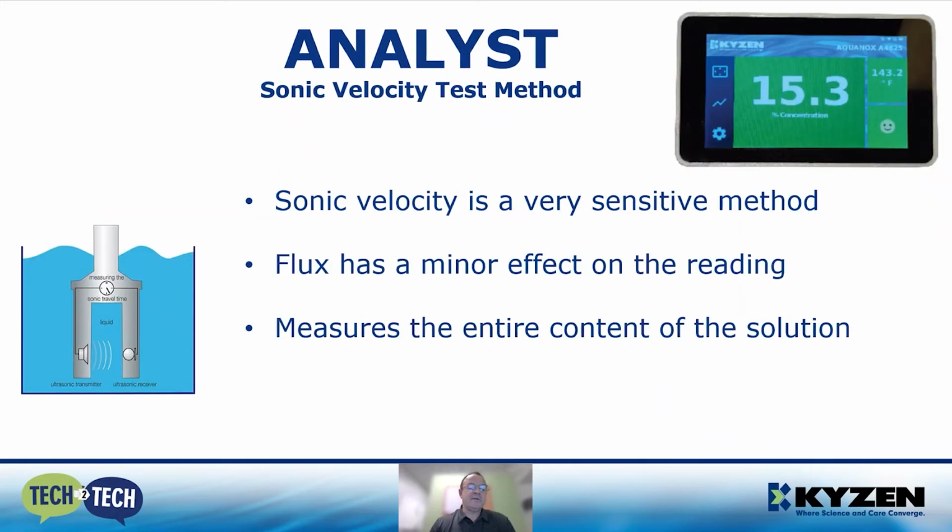So sonic velocity, as I said, is a very sensitive method that, as mentioned before, provides great accuracy. When flux or any soil is added, the concentration will go down slightly, but you can top up the solution, add a little bit to make up for that and get to the target concentration. This also has a benefit: it adds more bath life to your tank. So the product will last a little bit longer.